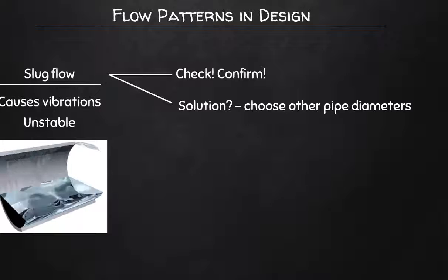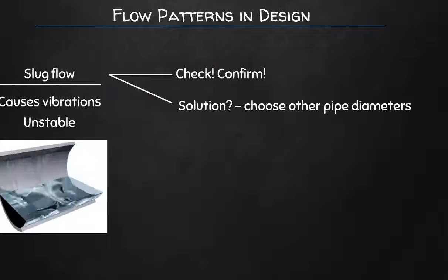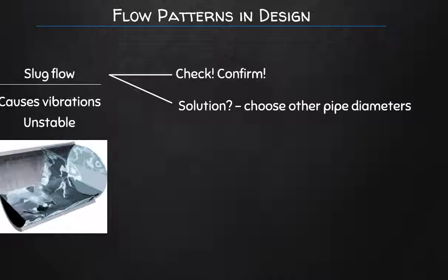Where some flow patterns are acceptable, others may not be very acceptable at all. In the case of slug flow in particular, the design should always try to prevent this form from occurring. As slug flows, you can think of the inertia banging into corners, etc. These types of flows are known to cause quite a lot of damage in pipes over time.